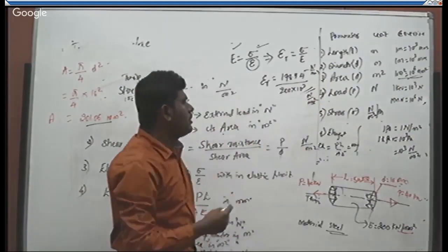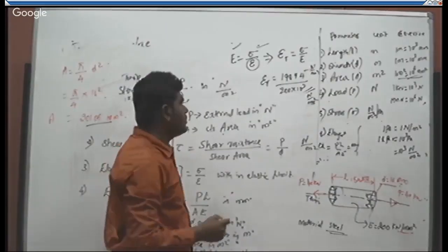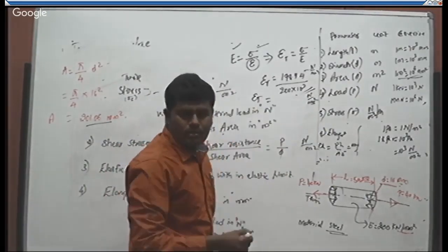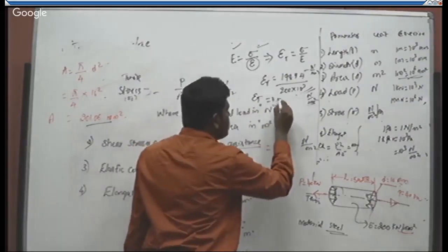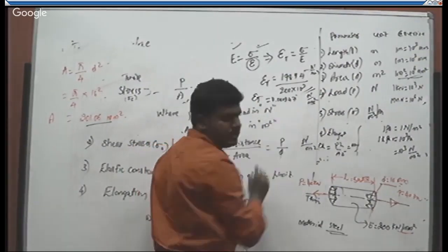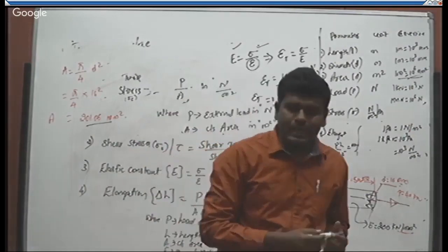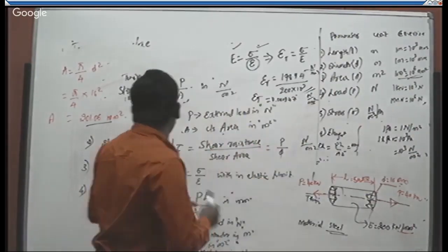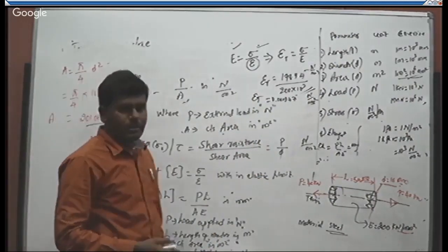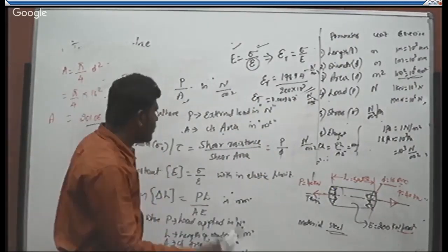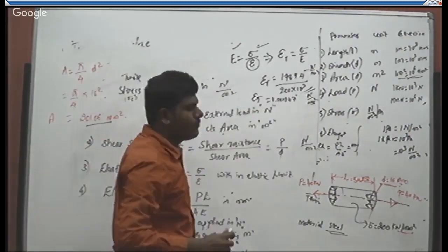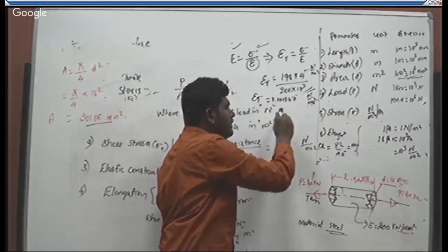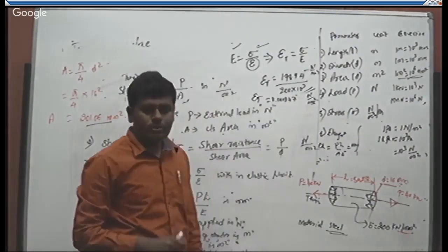You have to concentrate a bit while substituting the values. So we will get a strain of around 0.000947. Okay. So due to this action of 40 kilonewton across the area of 201.06 millimeter square, there will be an intensity of induced stress of 198.94 Newton per millimeter square. Due to these actions, it will undergo a strain of 0.000947.